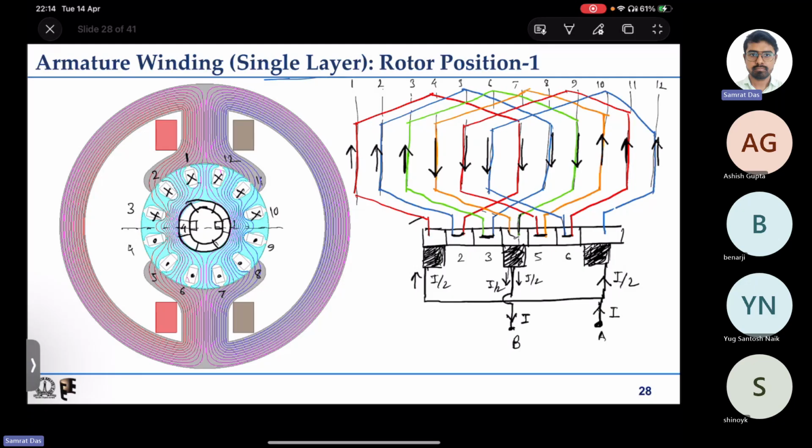Now let us go back to rotor position 1. So what happens if we move by some small angle, so that now the brush is actually touching two commutator segments rather than one. Again, mind you, the commutator and rotor are the ones that rotate. The brush and the stator field remain the same. So at this rotor position, for this winding connection, what is the induced EMF?